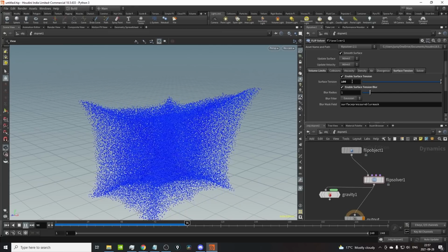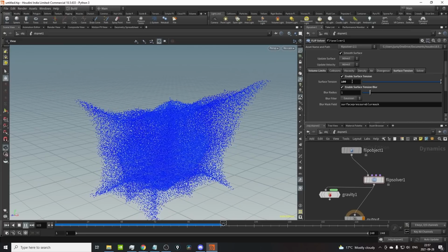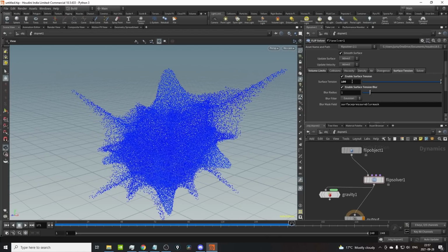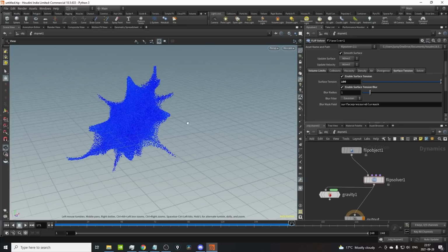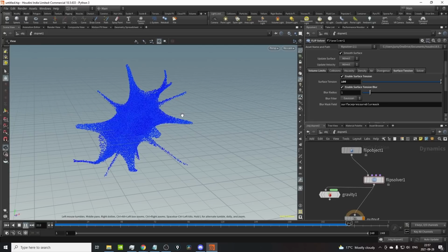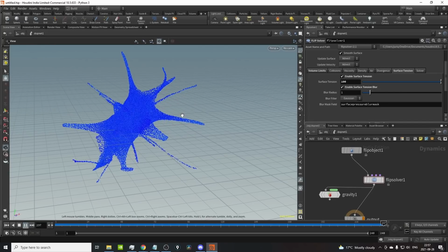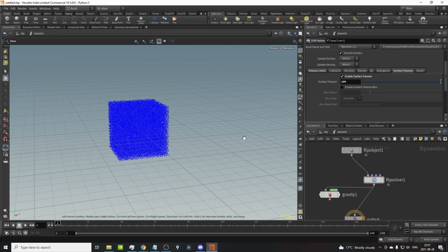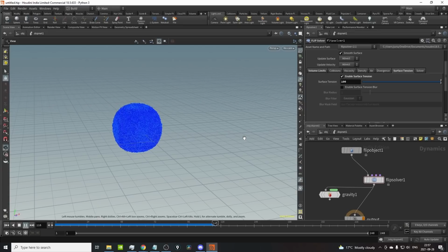So this to me just doesn't really have a place in standard water simulations. It does look interesting, right? It does make this really nice noisy shape. I just think in general that's not the kind of behavior you're looking for if you use surface tension, right? So I turn this off, and then we're just simulating surface tension like this. We're getting the averaging out, smoothing out those corners, smoothing out the spikes in curvature in our surface field, and we're getting a quite nice liquidy behavior.